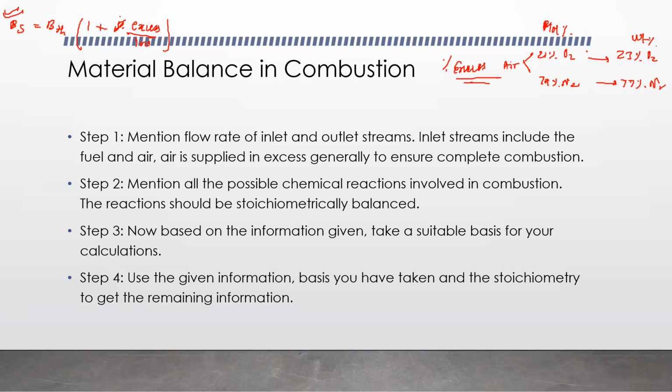All right, so remember this thing. So suppose if we somehow calculate oxygen supplied, that is basically 21% of air supplied. So let's say air supplied is X. So it's 21 by 100 of X, right? So from here you'll get X as oxygen supplied upon 0.21.